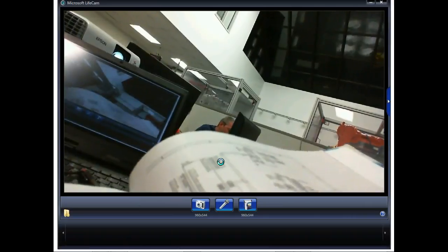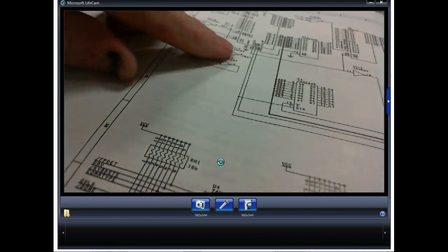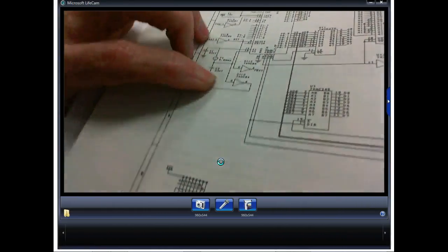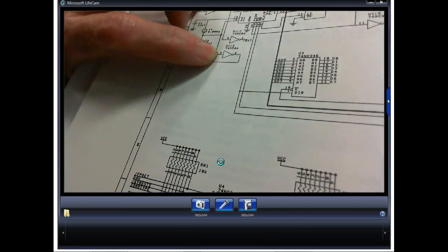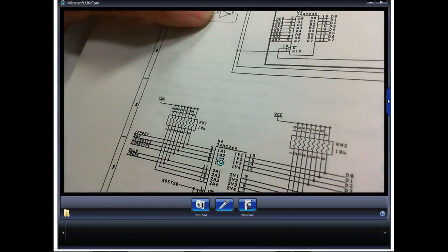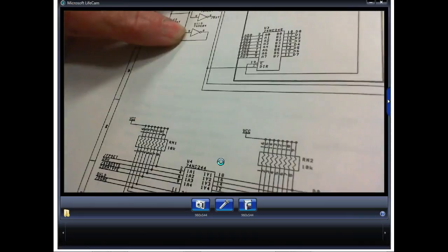Like they'll start, pin 1 would be A, the next coming down would be A, B, C, D, E. Y'all understand that, how they would do that? But look what they do. They put the pin numbers. So that means I don't have to figure out what pin number they use. They put the pin number on the schematic.